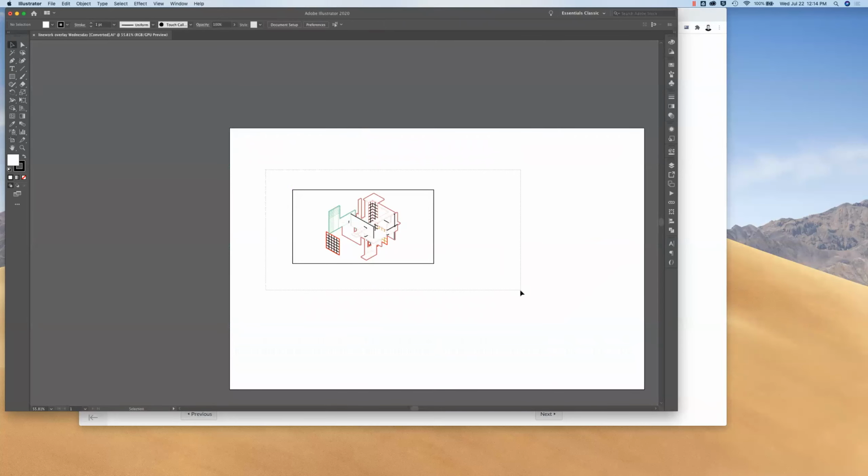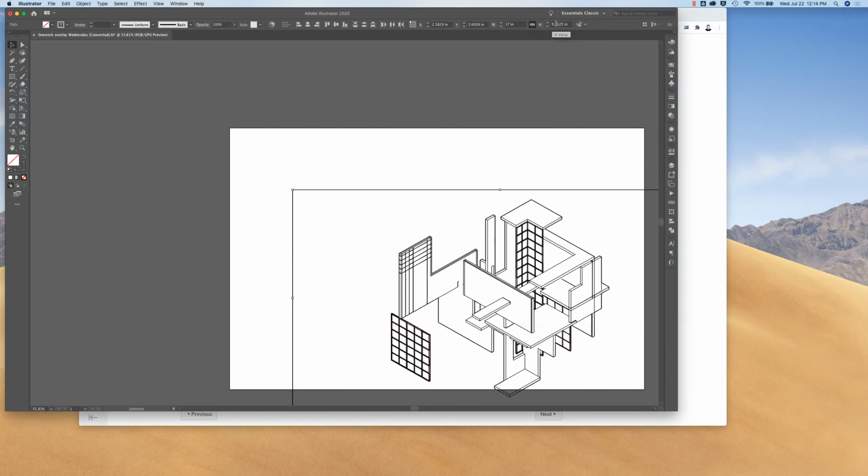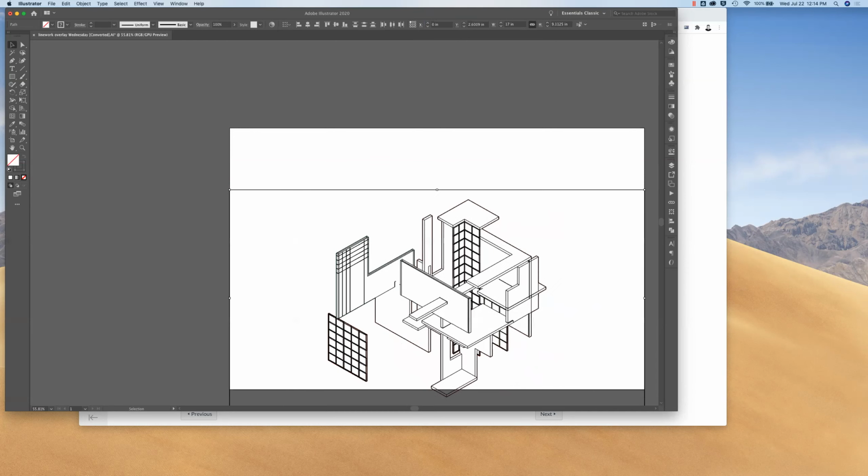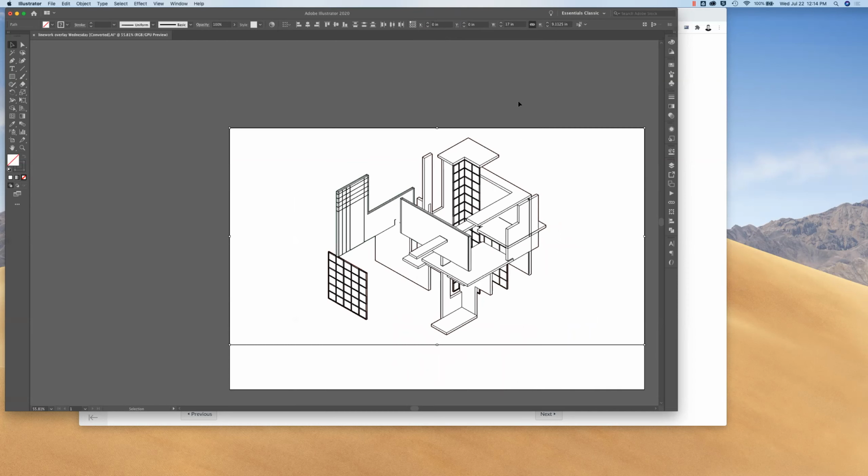Okay. Go ahead and take this drawing. I'm going to select it, and I'm going to give it a width and a height. So I'm going to say, okay, first of all, if I change the width, I want the height to be linked to it proportionally, so it'll adjust automatically. I'm going to tell it to make the width 17 inches up here, so the height adjusts along with it. I can also tell it that I want the top left-hand corner to be at the 0, 0 point of the drawing, so 0 on X, 0 on Y. All right.